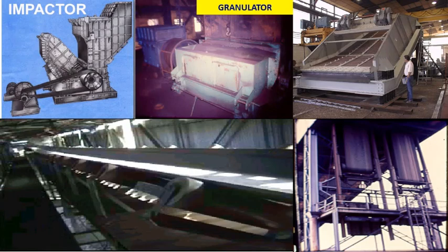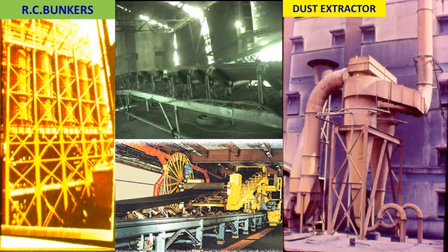There are granulated crushers, and these granulated crushers crush the coal into minus 20 millimeter size, and we have an arrangement to separate the coal fines generated during this crushing and fragmentation. Except for this coal dust, the crushed coal below 20 mm size is taken further by a conveyor system to the raw coal bunkers.